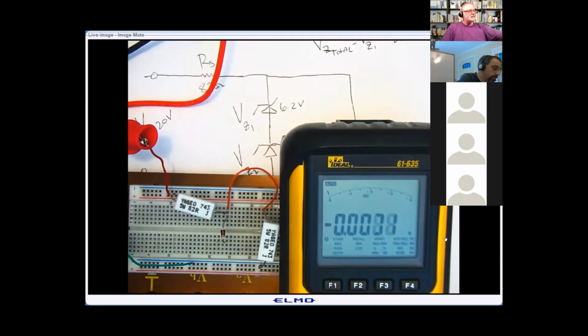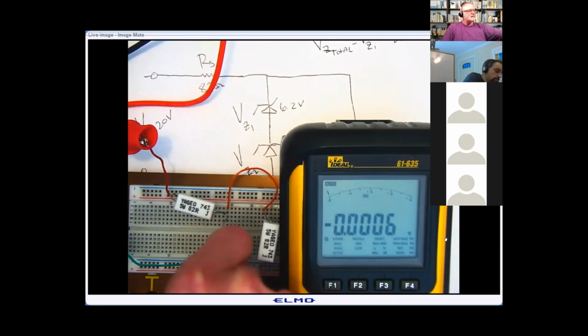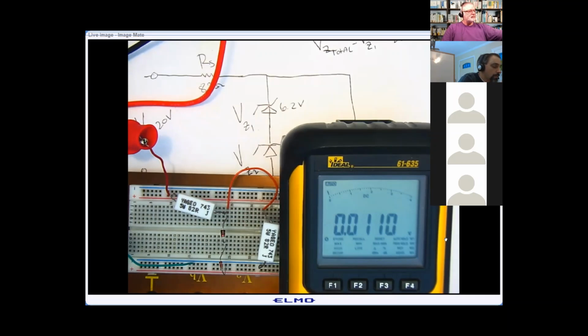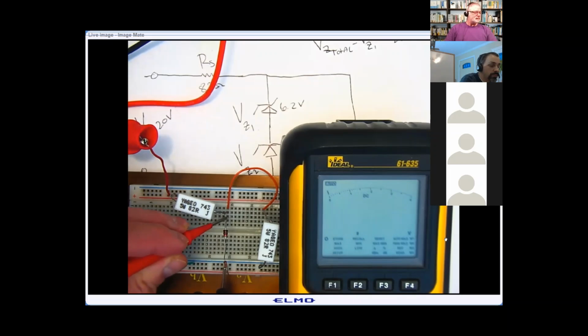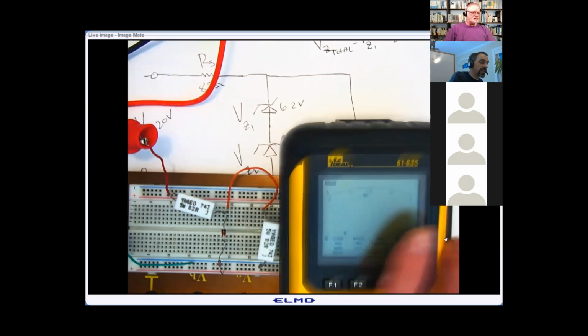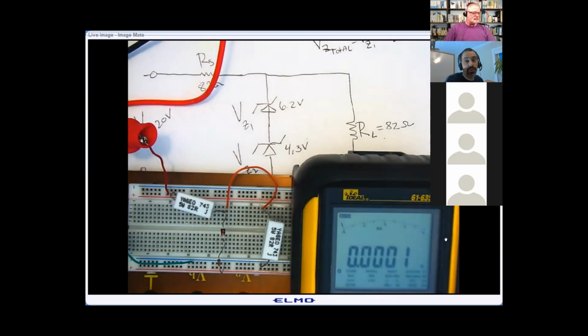I'm going to see if we get it up a little higher. That's a little toasty. And it's still giving me around 3.5. 9.8. So technically, we're supposed to be getting about 10.5. We get about 10 volts on it. We're off by a half volt. Not too bad.